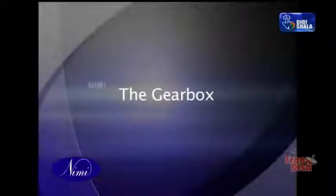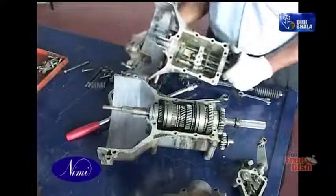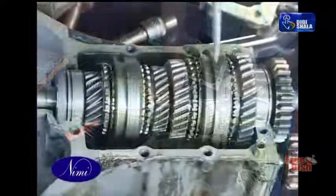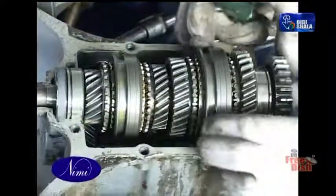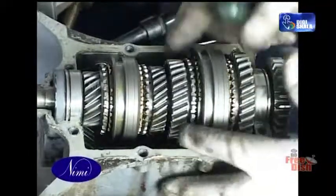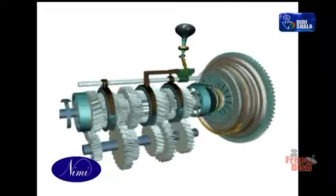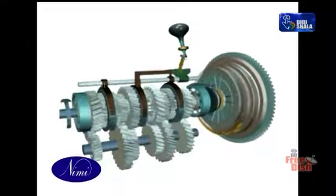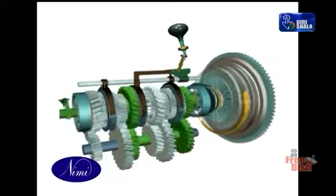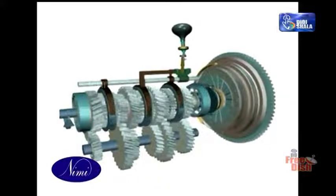The gearbox. Besides providing forward or reverse motion of a vehicle, the gearbox must overcome one of the drawbacks of the internal combustion engine, that is the poor torque output at low engine speeds. Gearing is provided either to 1. boost the engine torque, or 2. enable the engine to be operated at a speed where its output power is high.